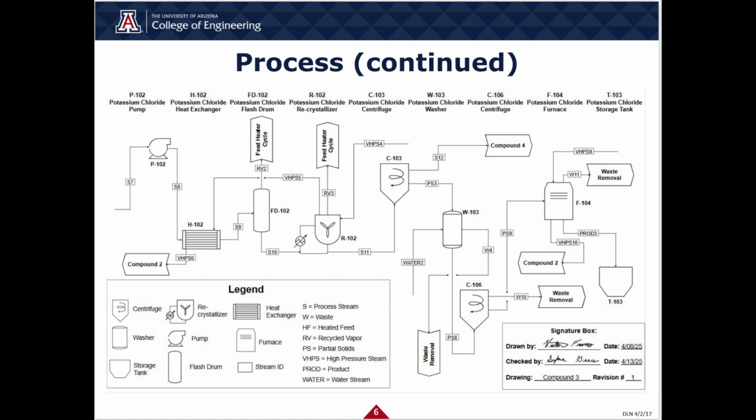After the salt crystals are removed from the main process, they contain impurities. As such, they go through a purification process. While each salt's purification process is slightly different, they mostly use the same methodology. Starting with introducing new liquid into the system. For sodium chloride and potassium chloride, this is water, while for the remaining salts, it's ethanol, as ethanol has different solubility limits than water. The new solution is then sent to a centrifuge to remove the salt impurities, followed by being heated in the furnace to vaporize excess liquid, leaving the salt at a 99% or greater purity.